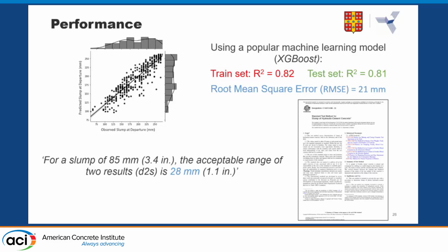The issue with slump prediction is not when things work well. When things work well, the AI model will always predict the trends in the data. And people at the batch plant usually have experience, so there won't be a problem. The problem is when things don't work well, usually when there are cement admixture compatibility issues. It's not reflected well in the data, like alkalis going up, C3A going up, something going wrong, metering at the batch plant not working.